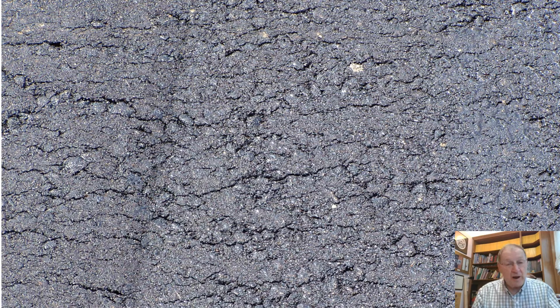They were too rounded, and so as a result, the mix would not sit still. The fix was redesign. You know, figure out what was acceptable that could be left in place, what had to be removed, go and do another mix design, still fine graded, still tight texture, but now more manufactured sand in it and less natural sand than what had been.